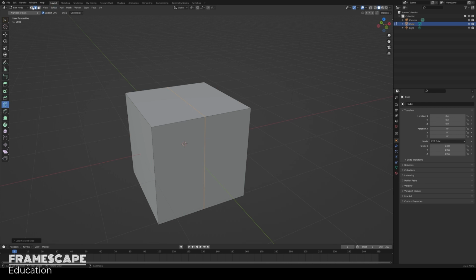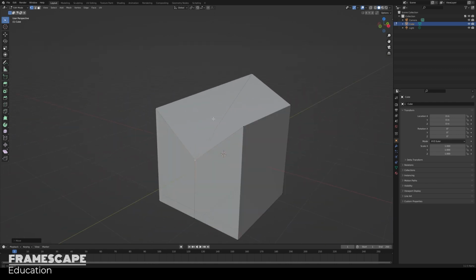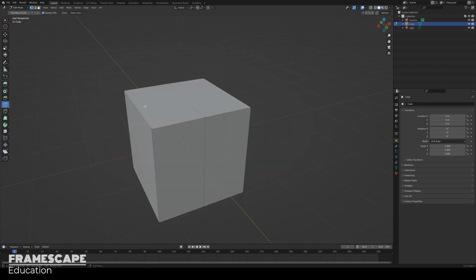If I move over now to vertex mode, you'll see that vertex points have been added. And if I return to select mode, you'll see that I can click on these vertex points and move them around. It's essentially added more detail to this shape so that I can further create more interesting shapes. The yellow indicator line will jump around the shape depending on where you put your cursor. When you click, if you don't let go immediately, you can move that cut point around, and it's not until you let go that the actual cut is made.